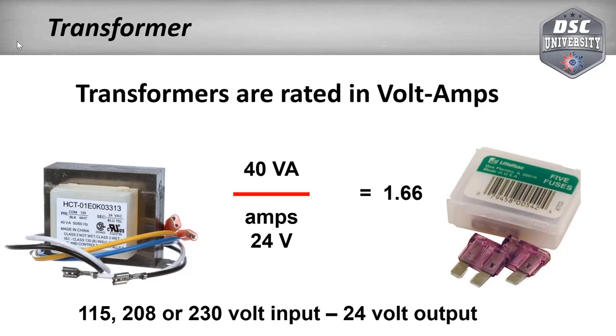So it's a very low voltage, low amperage control voltage, so it's not dangerous. It's not something that, if you grab hold of it, is going to hurt you. And we also have the fuse, which we saw was plugged into the board. The fuse is on the 24-volt side, so if something gets short-circuited, instead of burning up the transformer, it'll pop the fuse.